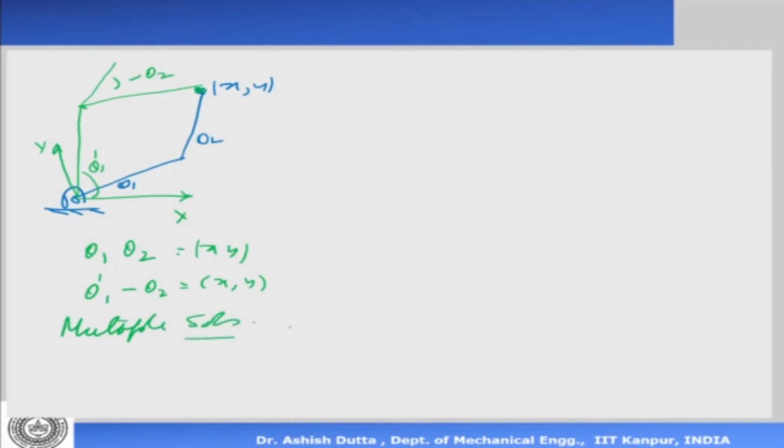If you have higher degrees of freedom, you will have more solutions. Because of this, we do not take the inverse there, because you will get a plus and a minus. Now the software, if you're writing a computer program, will not be able to distinguish between minus and plus. This part causes the problem, because cos of minus θ2 is equal to cos of θ2. As far as the computer is concerned, it cannot distinguish. But as far as the real system, they're all different. You can see minus θ2 is up there, and θ2 is here.